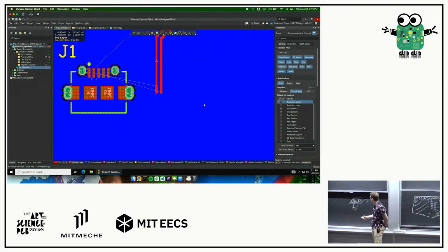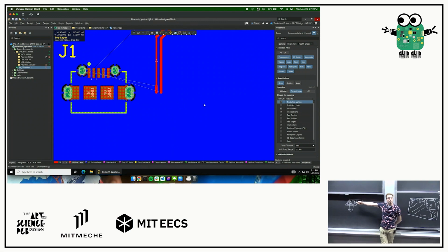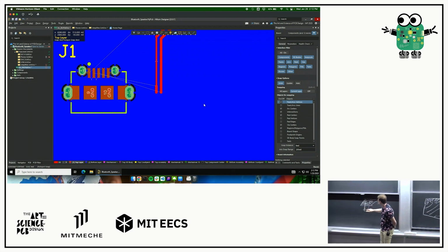But the primary reason is, remember, what did we do yesterday in lab? What was the first part of the lab that we did? We stenciled our boards, right? We put solder paste on the whole thing. If I go to assemble this and I put a thin layer of solder paste on the whole thing, and then I have this nice little hole that's made of metal here, what's going to happen when I reflow? Where's the solder paste going to go? It's okay. Where's it going to go? It's going to go in the hole, right?